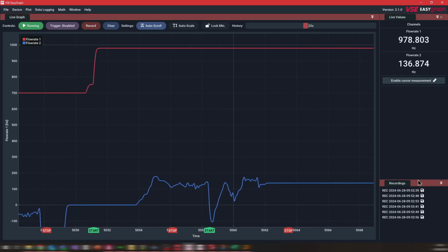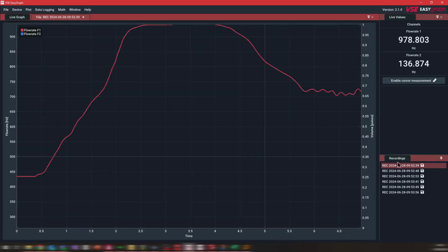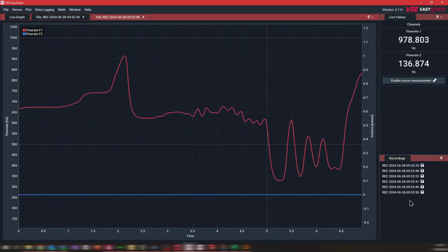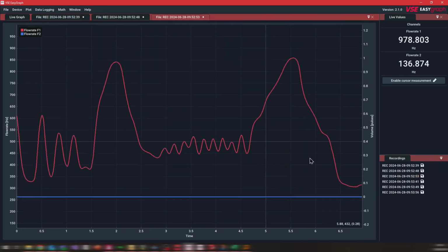As a result, you will get multiple recording files which you can view and analyze, and in these files you can see also that we have the pre-trigger duration active, so we have a bit of recording just before it even happened. So here is the 800 trigger mark, and you will see it's about at 2 seconds because we specified 2 seconds pre-recording time.